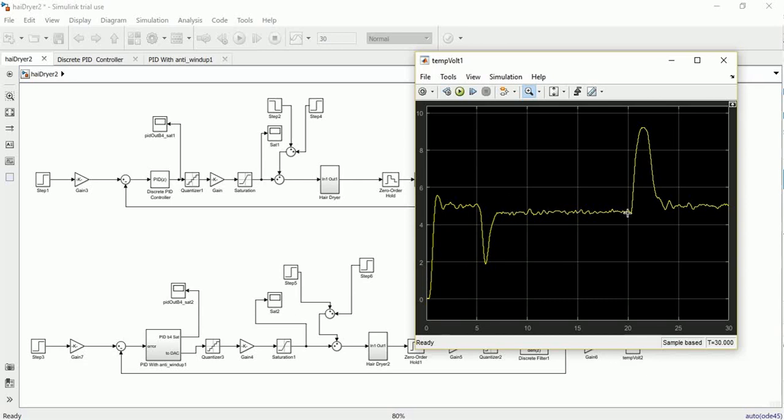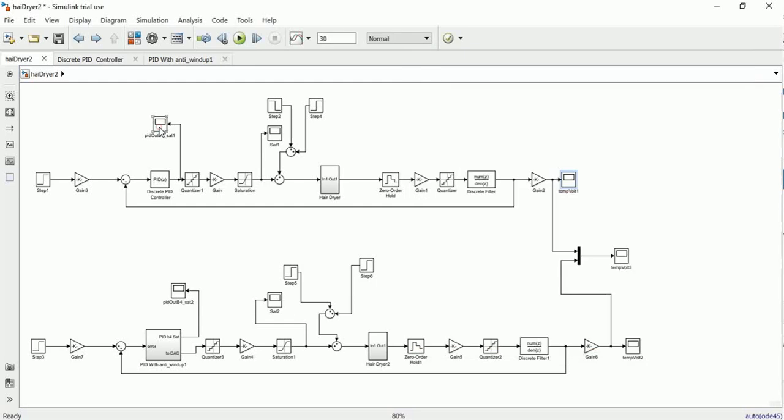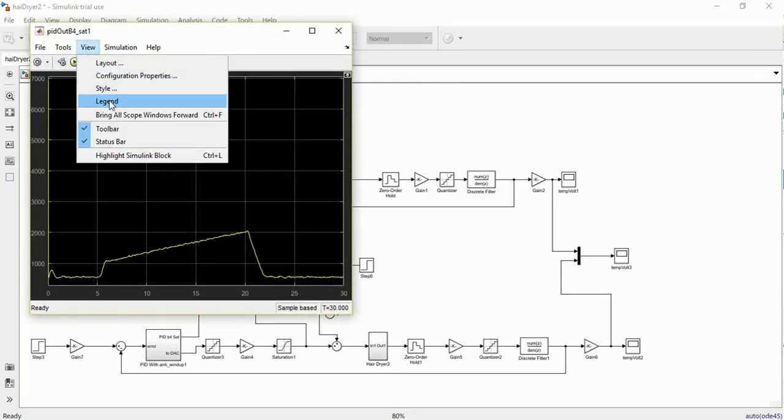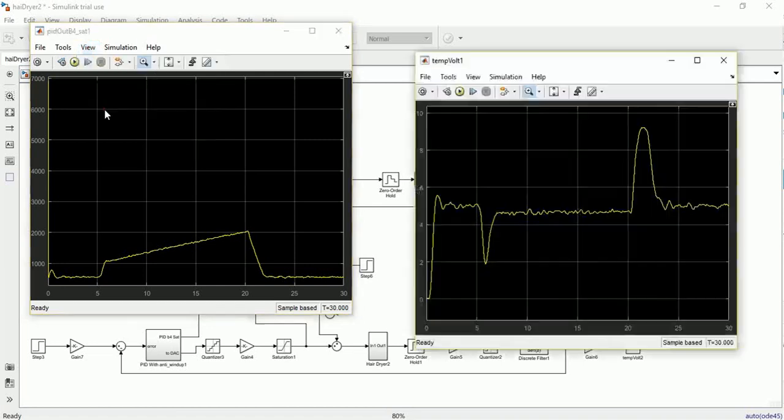And when the disturbance is off, then everything should come back normally, but there is a big transient here with a big overshoot, and then it tries to come back to the 5. At this point, yes, it gets 5 because the disturbance is gone. And the important thing here is why this transient is not like this transient here, at least. It is worse, and there is an explanation for that, and the explanation is called integrator windup.